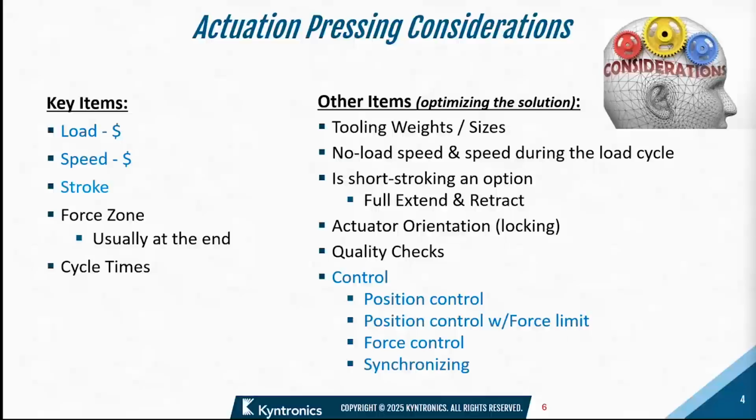Orientation: if it's pointing down, you may want to lock it for safety reasons, those sort of things. So control, we have various modes of control: position with force limit and force control. We'll talk about those, as well as synchronizing. So these are all things to consider while you're going through and figuring out what the right solution is on your press.